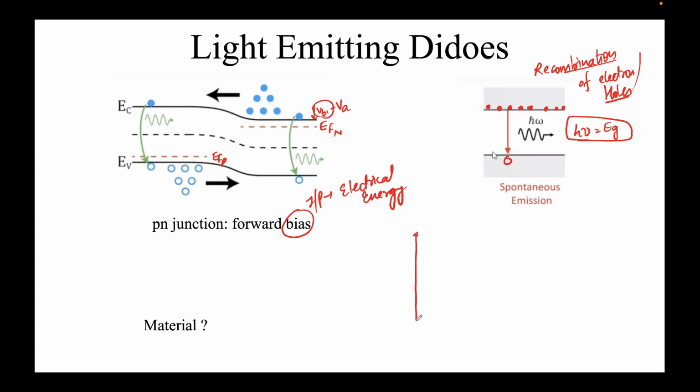So what we have here, first I'm drawing the direct band gap. So this is your E-K diagram, energy versus K, the wave vector. This is your Ec, and your Ev. So what you can clearly see is that the top of the valence band is coinciding with the bottom of your conduction band. This is the example of a direct band gap. Now I'll draw an electron and see how it behaves.